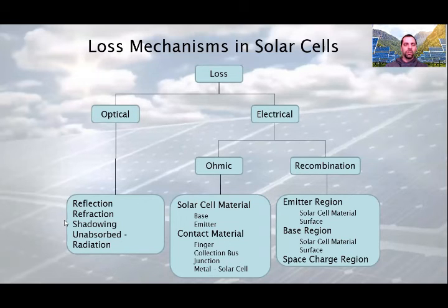The recombination losses are defined by various processes in the semiconductor: radiative recombination, luminescence, Auger recombination, recombination on the semiconductor defects and impurities, and surface recombination.